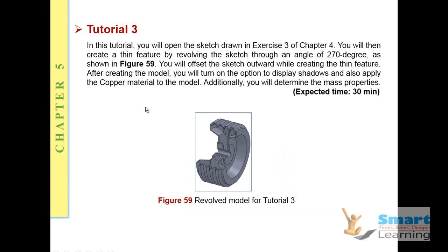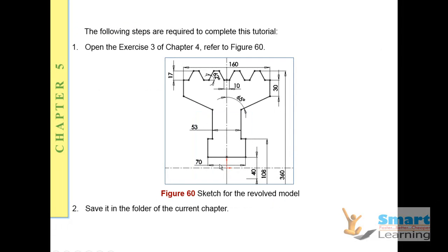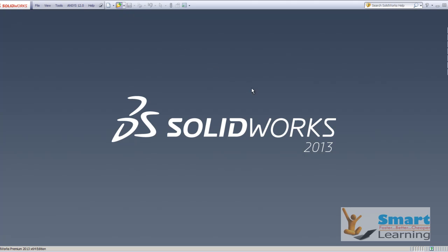And in this particular tutorial, we will see how to create the revolved sketch, and then how to revolve it with respect to the axis and create this solid feature. So this is the central profile with respect to which you are going to create this feature. So for understanding this, from your exercise folder, you can get this particular model.